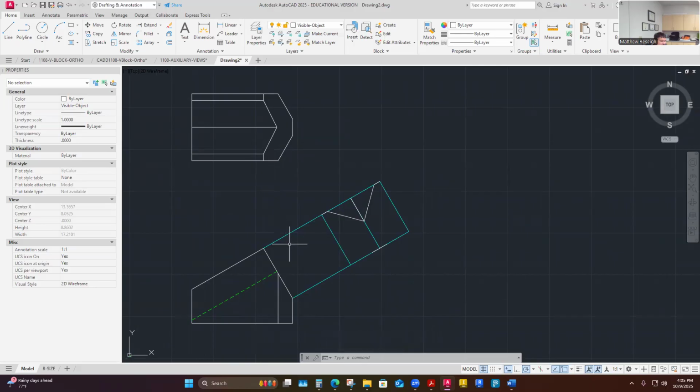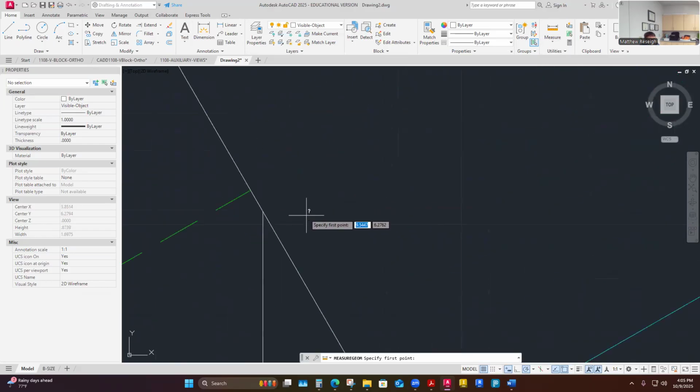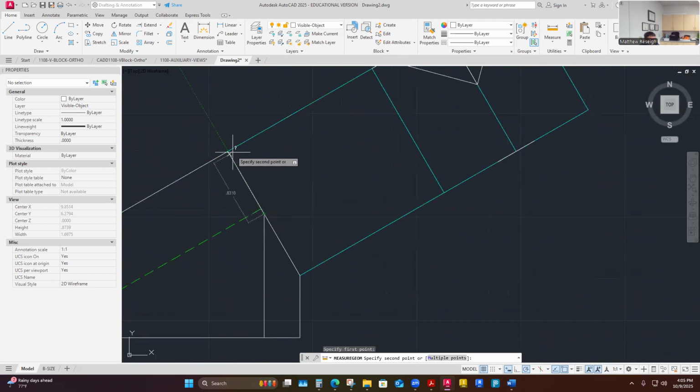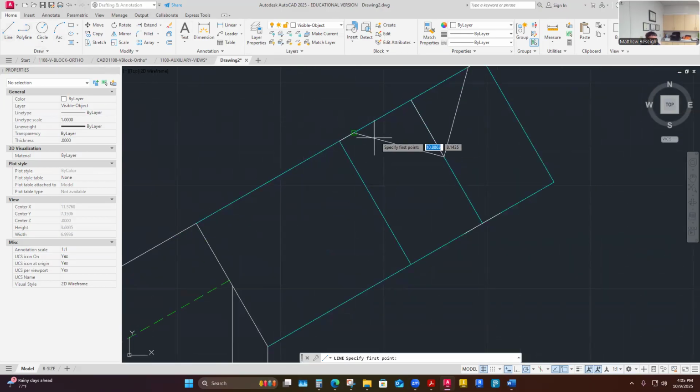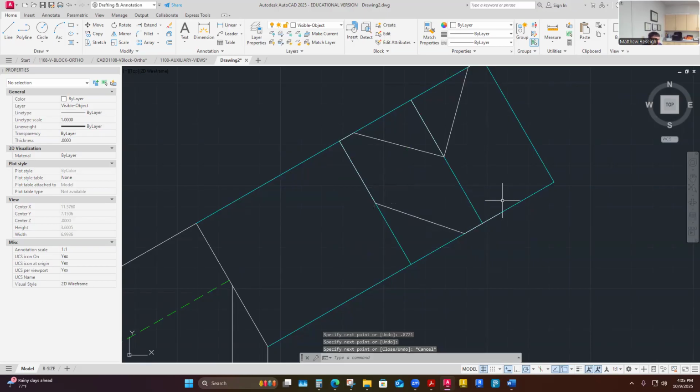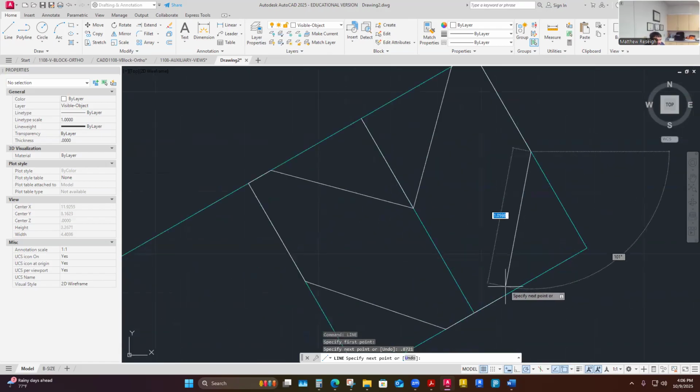I don't have it in the top view, but I do have it here. What I want to know is how long this is, where it changes from the front view plane. This dimension, 0.8721, is what I want to type in right here. So 0.8721, and then it comes back to here. And then I could mirror that across, but I think I'm just gonna draw it in, which is also 0.8721, and then back to here.